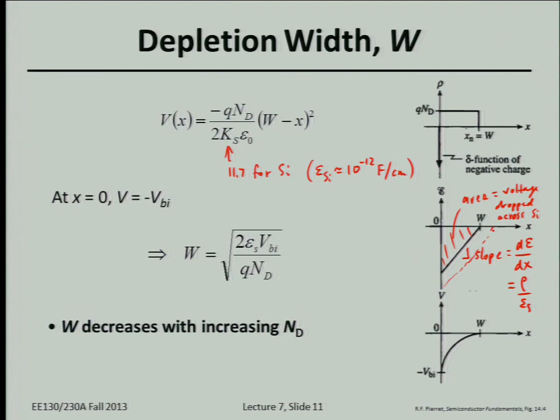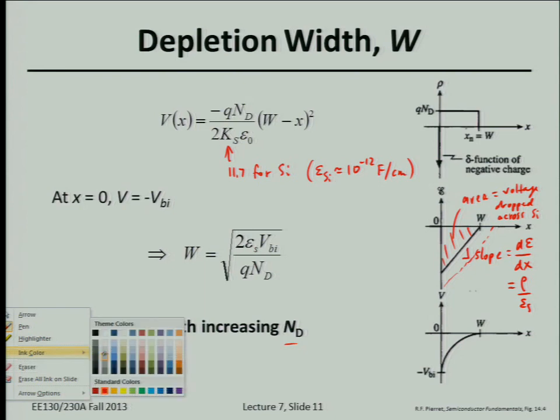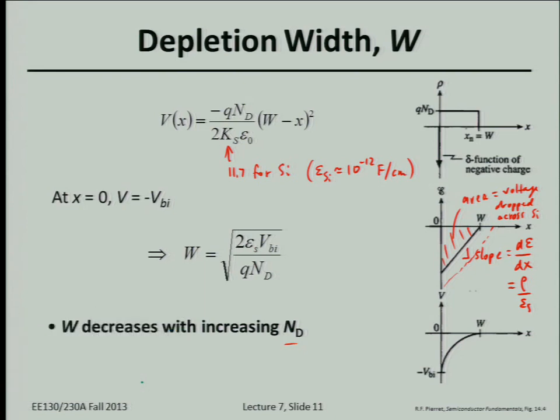Okay, well, what about increasing N_D? Qualitatively, on this E versus X plot, okay, let's do that. How would the charge density plot change if we increase N_D? Oh, okay, like this one up here, the very first plot. Yep, the doping concentration goes higher. Yes, so actually I drew it wrong. It'll be like this. Okay, because the built-in potential will change a little bit because the Fermi level is going to be different if you have higher doping. So you're absolutely right.